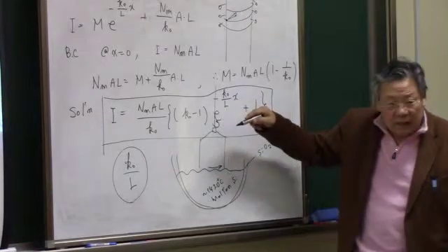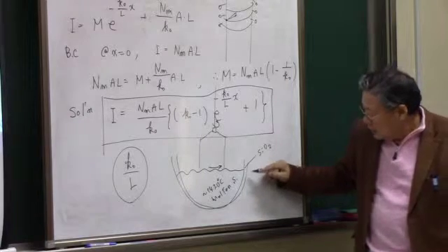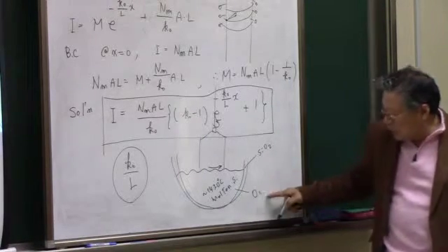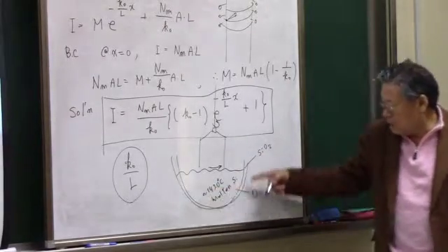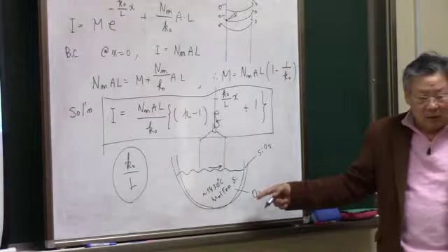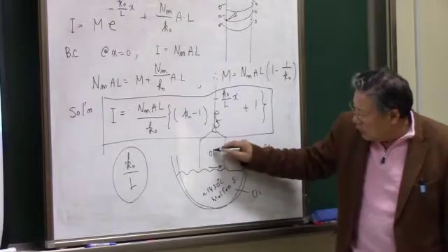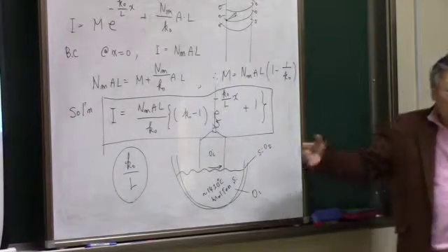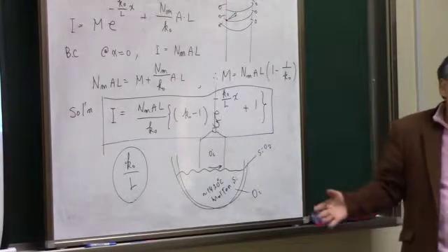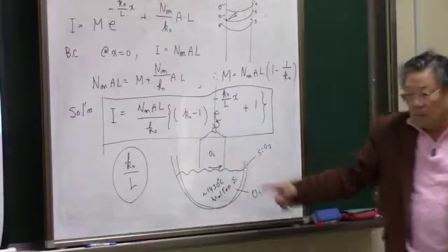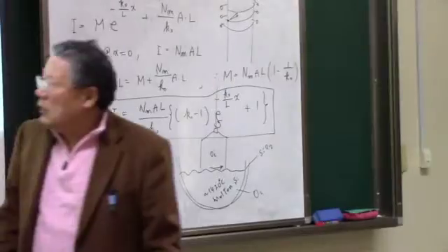We have to rotate this, and one of the drawbacks of this rotation is the incorporation of interstitial oxygen into the molten silicon coming from this silica vessel. Okay, and then that interstitial oxygen is going to be incorporated into the solid silicon during the freezing process. But this is not a trivial amount. As you can see, it's 10 to the 16th or 10 to the 18th.